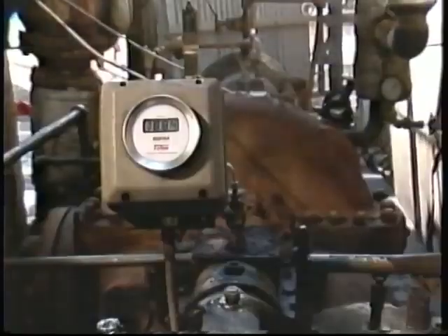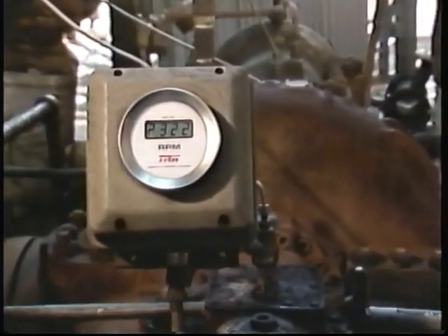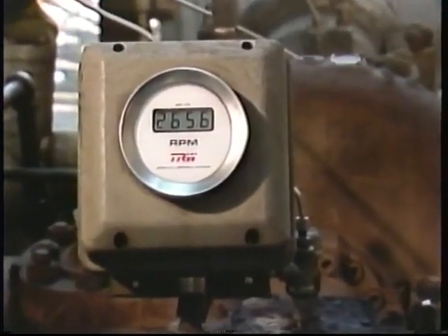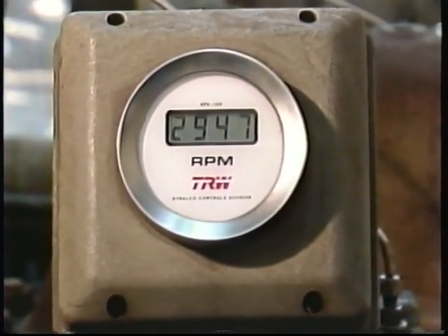The speed of a turbine must be controlled within the limits that the turbine is designed to handle. If the speed increases beyond the maximum limit and is not controlled, the turbine could literally fly apart. On the other hand, if the speed is too low, the turbine won't provide enough energy to drive the equipment. It's also important that the speed be maintained at a constant level during normal operations. Fluctuations in the speed are inefficient.